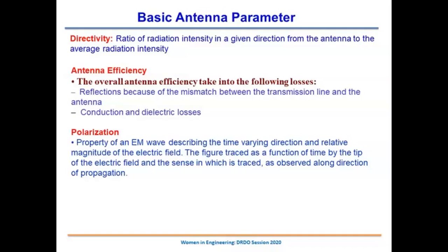And in the horizontal polarization, for example, if ships are there, the cross section of the ships, as you see, is horizontal. So there you prefer horizontal polarization. But I would like to tell that there is still very vast ambiguity on what polarization to choose for radars. But this explanation slightly brings out why polarization is important.